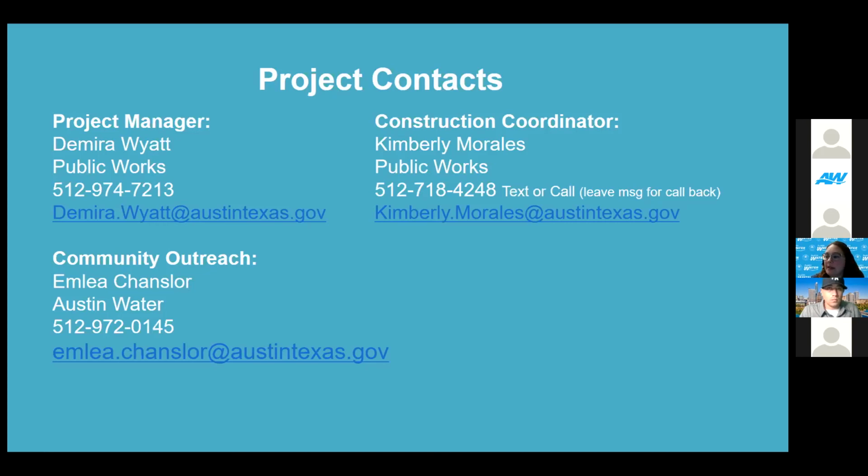With the new water lines coming in, is it possible for small debris like sand or pebbles to get into our residential plumbing? So who wants to take this? I'll go with it. So as part of our process, Terry, when we put in new water lines anywhere across the city, it is our responsibility to flush those lines before they actually become active. One, to ensure that nothing has gotten in there, and that everything is flowing, and that you have good, clean, serviceable water that is going to the home.